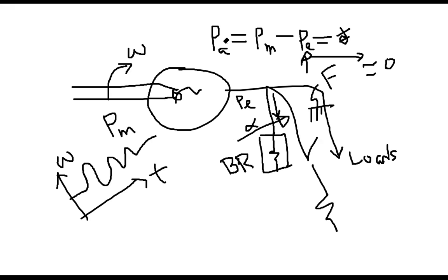But what is happening? Because I am controlling with the help of alpha, there is continuously switching. This power is continuously changing, and that is causing some oscillation. It is kind of vibrating until it is fixed. Why I am bringing up this point: there are some examples where the shaft system has been cracked, broken, or deformed. So the impact will go on the shaft system. That is the negative thing of this method. Otherwise everything is positive.